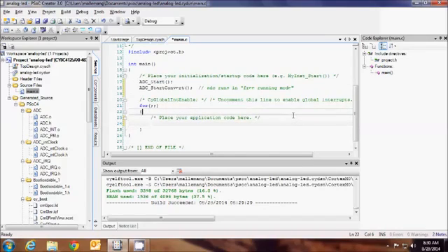So here's where we'll get the value. Oh, right, we're going to need a variable to hold the converted value, because I want to limit check it and limit it to the valid range of 1 to 2047 roughly. I don't want it to go as low as 0 because I'm going to use it for a time delay value.